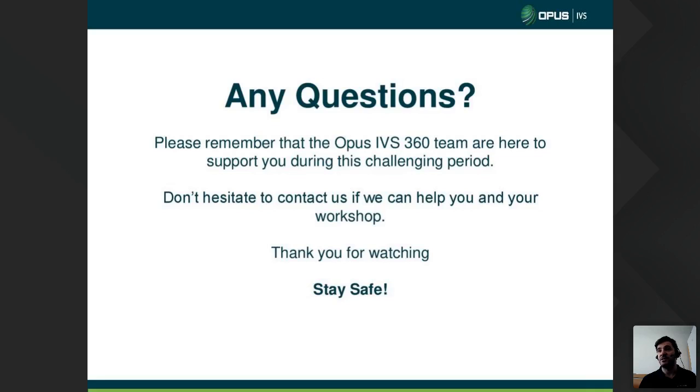Gil has asked if the Autologic has a graphing mode to be able to do any oxygen storage test on the cat. No, I don't think all of the options are there, but again, you can make it much simpler for yourself. On that particular engine, for example, on EcoBoost, you just put the emissions probe on the exhaust and check the condition of the emissions. And if they're within spec, then you have the O2 sensor after cat tested. I'm told they're rather common because dealers are keeping them in stock because they see quite a few of them.